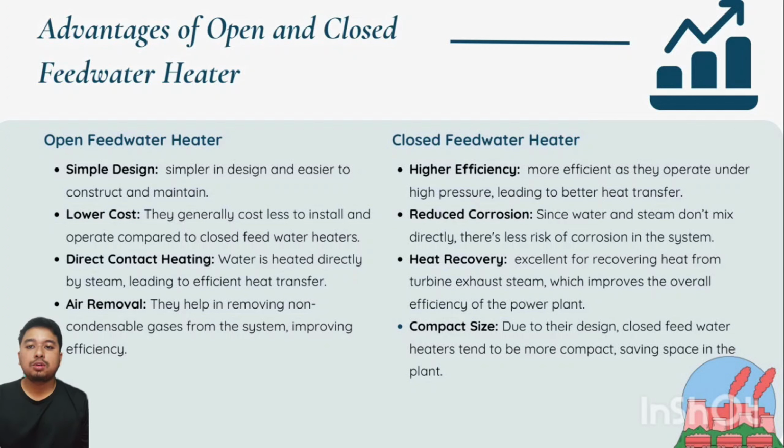Second, lower cost. Due to their uncomplicated design, open feed water heaters are generally cheaper to install and operate. They require fewer materials and less labor for construction, leading to cost savings. Third, direct contact heating. In open feed water heaters, water is heated directly by steam. This direct contact allows for efficient heat transfer, as the steam condenses directly into the feed water, transferring its heat energy quickly and effectively. Lastly is air removal. These heaters help remove non-condensable gases such as air from the feed water.